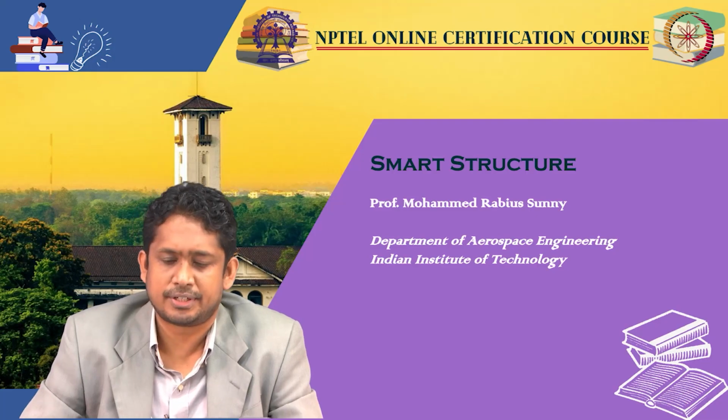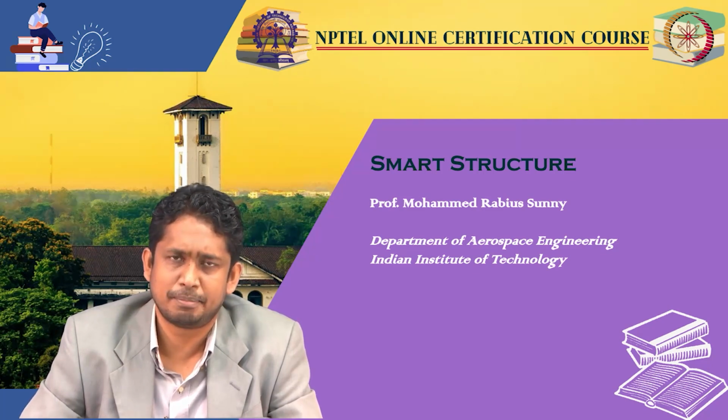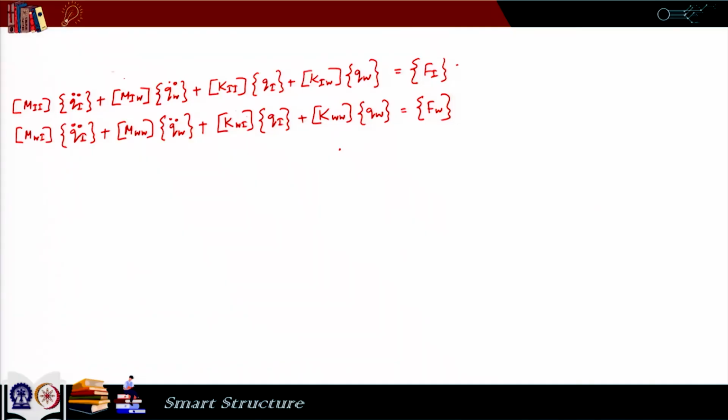Today we will continue our discussion on analysis of composite laminates which have piezoelectric patches. In the previous lecture we saw a case where the deformation was purely in plane. It was because our actuators were actuated in such a way that it generates only in-plane force, and also the composite laminate was symmetric. Now today we will see a pure bending case.